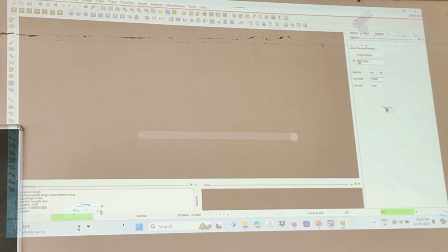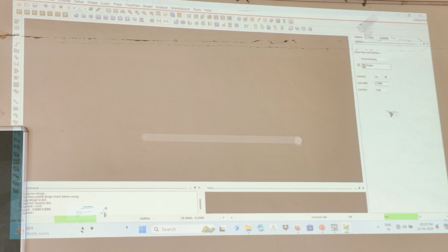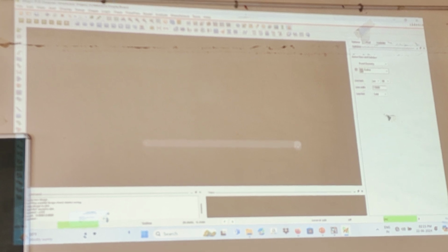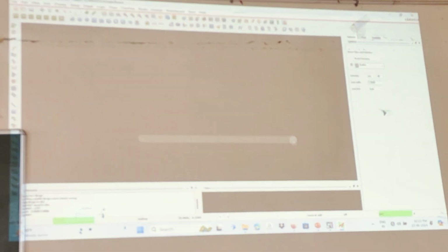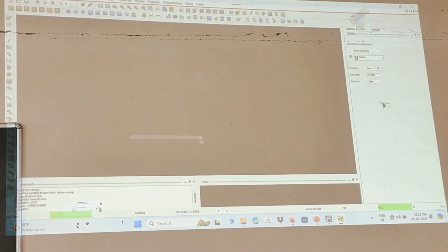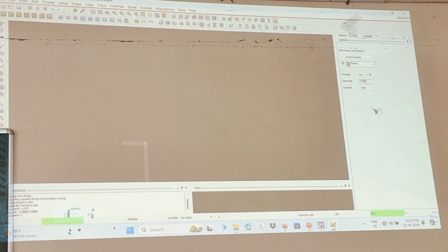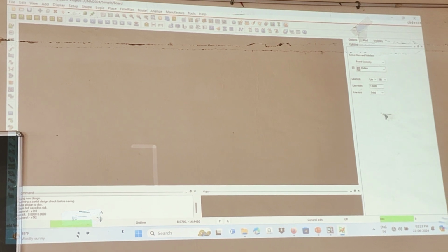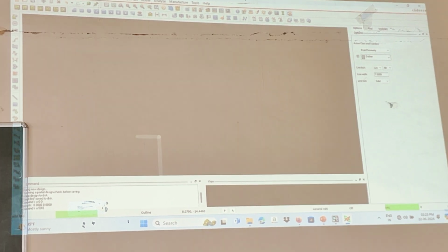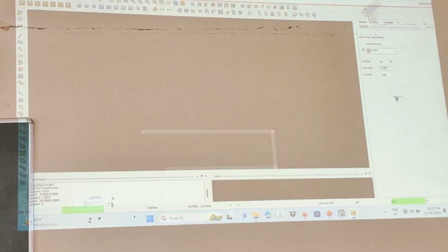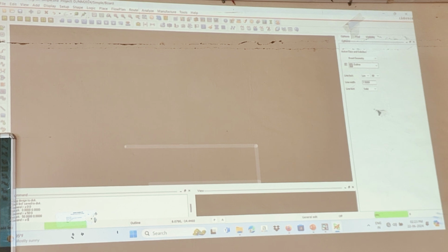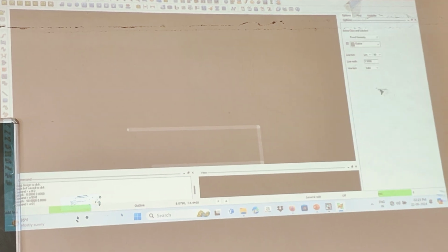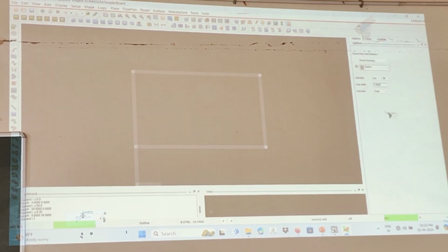And here I am going to choose the approximate dimension of the board. PCB is 50 mm cross 30 mm. So I am selecting the next placement where I have to place in the command window, with x space 50, x direction 50 and y direction 0, and press enter. Next x space y direction 0, x is 0 and y direction of 30 mm, press enter.